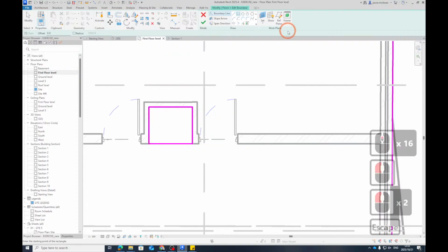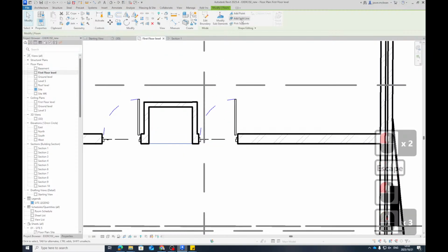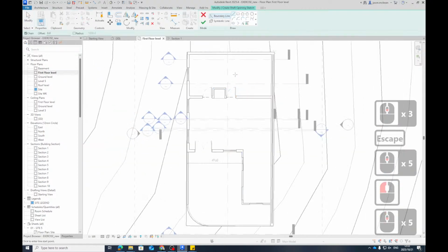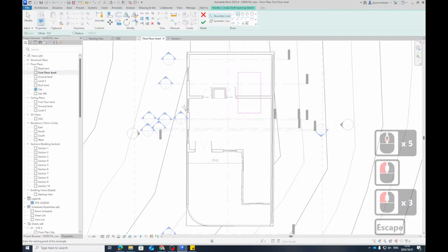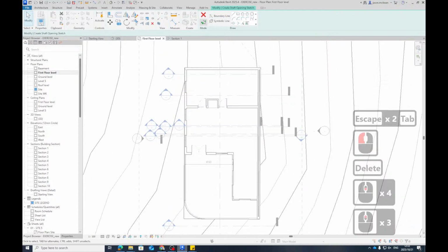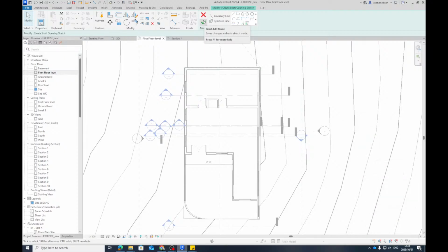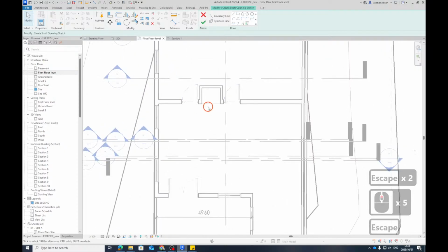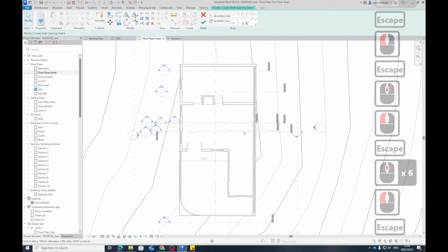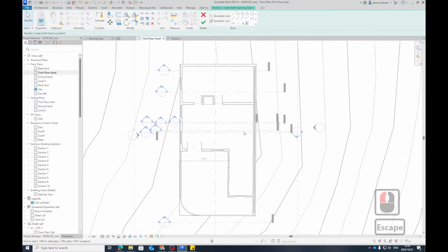There is another tool where you can add shafts. In a floor, you can add shafts, a shaft you can put through the whole building, but it comes with a catch. Sometimes when you're trying to draw other floors over, it will shaft everything. So a shaft is a shaft. I prefer to do this rather because I have more control. Just go individually, and you can copy this floor slab to the ground floor very easily.